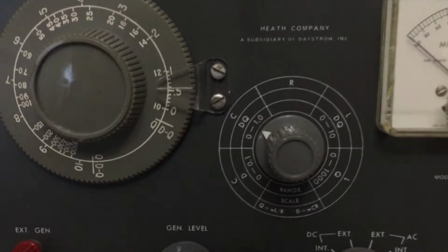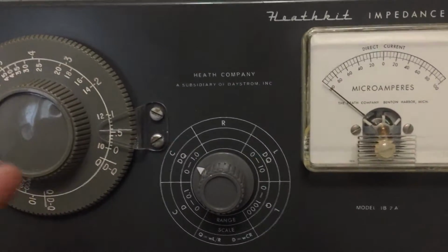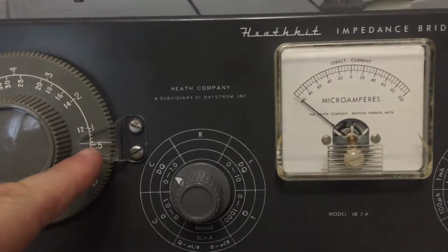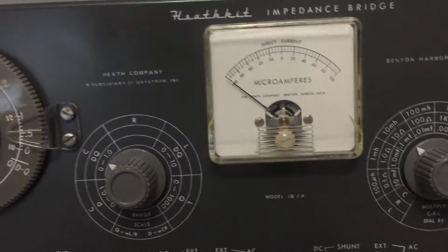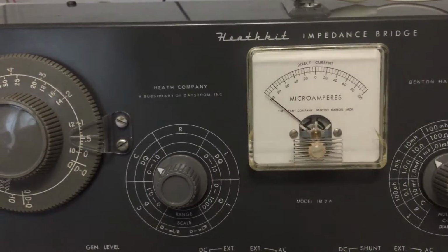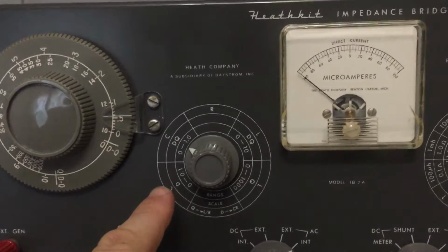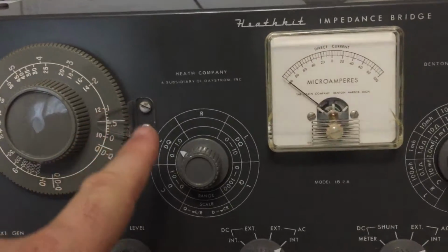The purpose of this one is to demonstrate a particular function of this machine, because the Q for this condenser happens to be less than 1. And because it's less than 1, and you'll take my word for it, it happens to be dialed in at exactly, on this knob, 0.6, right? So 0.6 shows the highest amount here. Now, one of the functions of this particular impedance bridge is that when it's less than 1, you have the ability to have an extremely high resolution for values under 1, right?